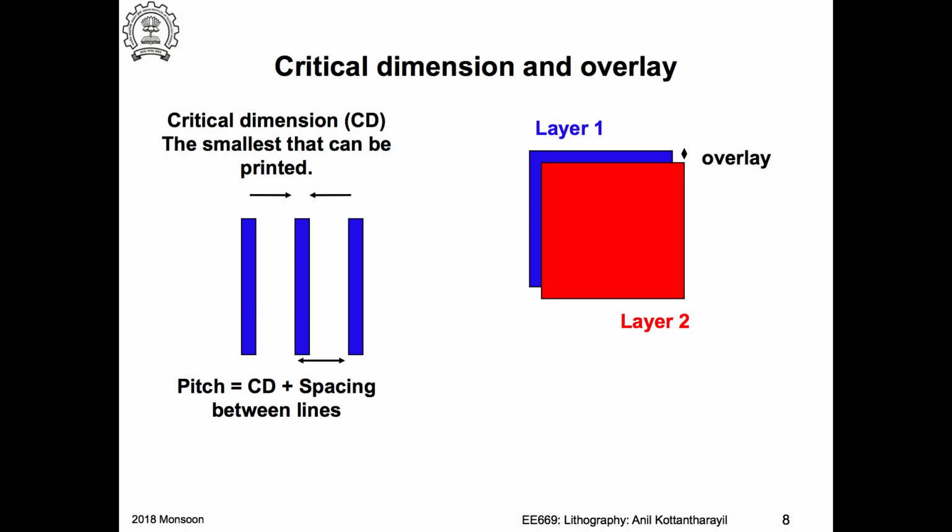Diffraction, but that leads to what? Diffraction is also present if I have a single piece, right? Just one isolated line. It will come from the interference of the diffracted light. Okay? So, when you talk about the critical dimensions, it's very important to make this distinction, because in a VLSI circuit, you want to pack the devices very densely. Very important consideration.